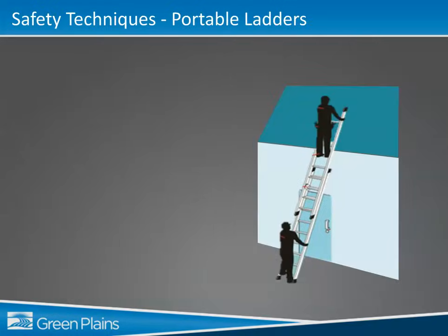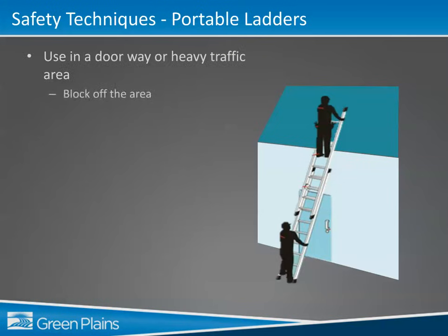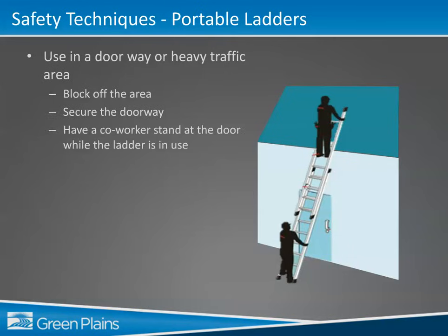If it is necessary to use a portable ladder in a doorway or heavy traffic area, use precaution and block off the area. Secure the doorway or have a coworker stand at the door while the ladder is in use.